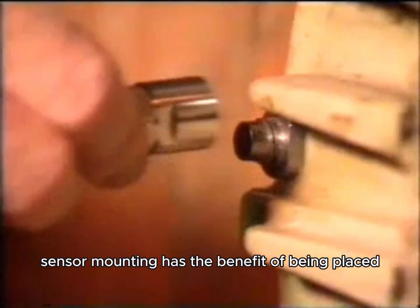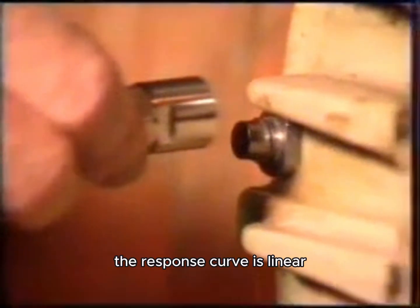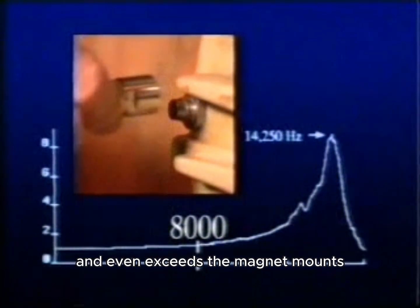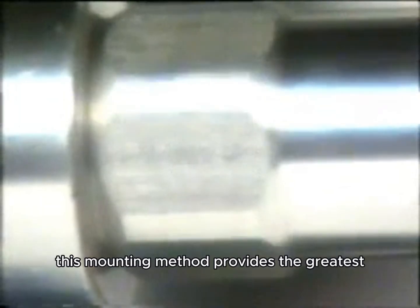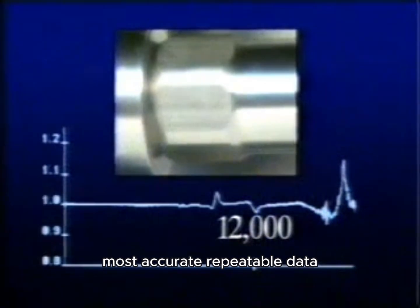This Quick Connect sensor mounting has the benefit of being placed at exactly the same location from one survey to the next, and it goes in place quickly. The response curve is linear over a longer frequency range and even exceeds the magnet mounts. Another method of mounting sensors is to stud mount the sensor in a pre-drilled, pre-tapped hole. This mounting method provides the greatest linear response range and will give the best, most accurate, repeatable data.